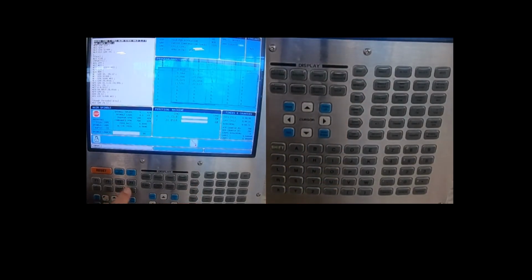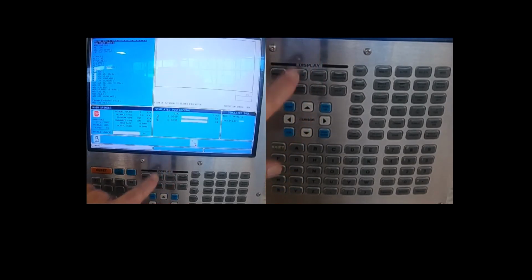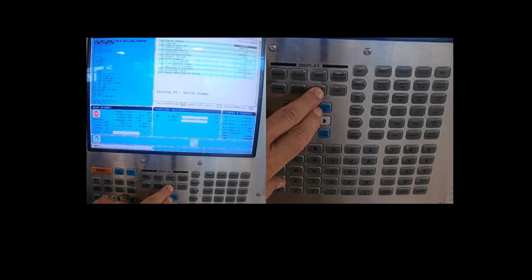You can also, from memory or edit, hit settings graph, and that's also going to take us to the same location. It's going to do all the exact same functions, just two different ways of doing it. We can either be in memory and hit setting graph, and sometimes you have to hit it more than once, or from the edit screen, we can hit cycle start, and it's automatically going to move us into graphics.